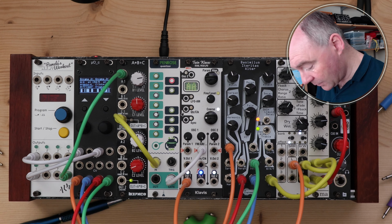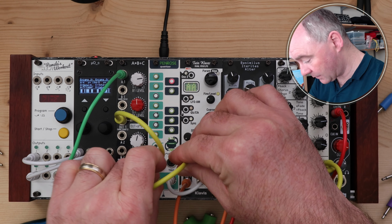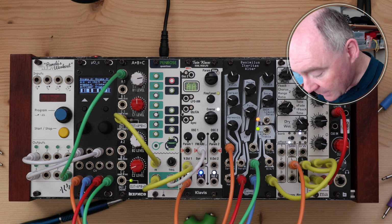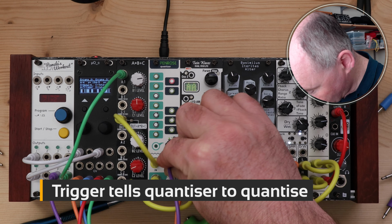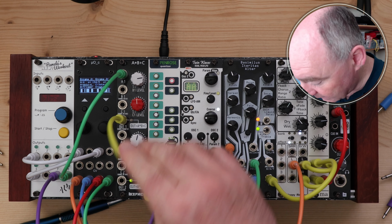And then what I want to do is take the output of the quantizer into the volts per octave input here, so we can play a melody. And then we just need a trigger. So output 7 here, I think I've set this up as a trigger. Every time the trigger goes into the quantizer, it'll quantize it to the selected scale.